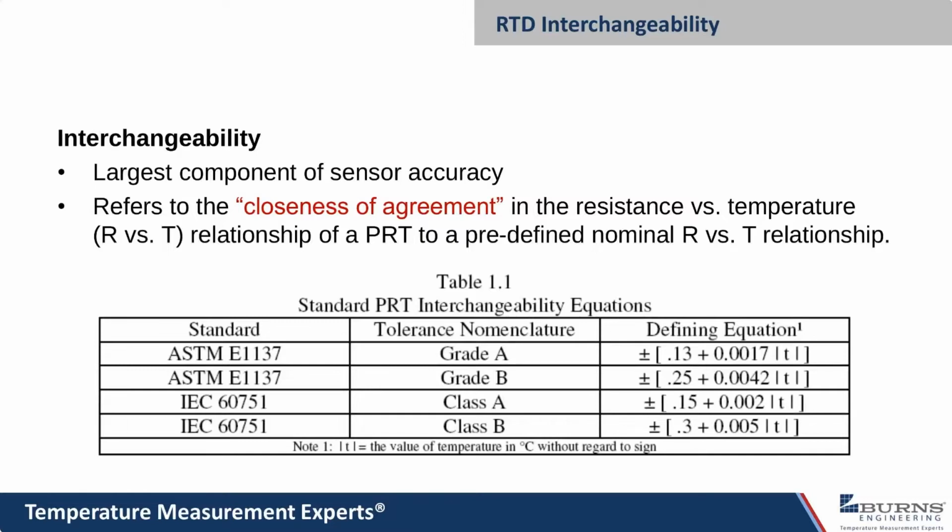Some are better at higher temperature measurements, and some can be a little more accurate, like the type T. There's also the type R, S, and B as in Bravo thermocouples. Those are made with one platinum conductor, and then the other is a platinum rhodium alloy. And those are capable of very high temperatures. They'll go up to, I think it's roughly 2000 degrees C.